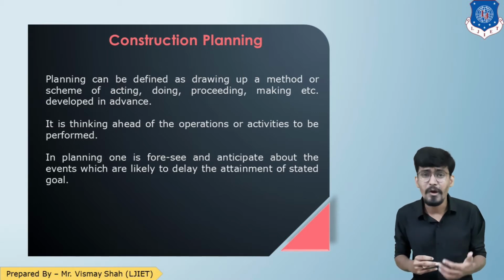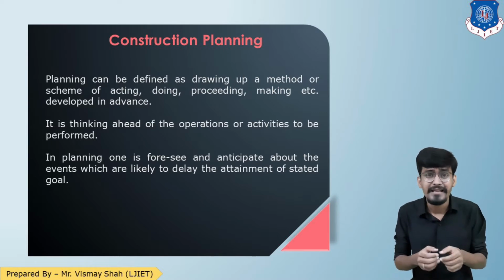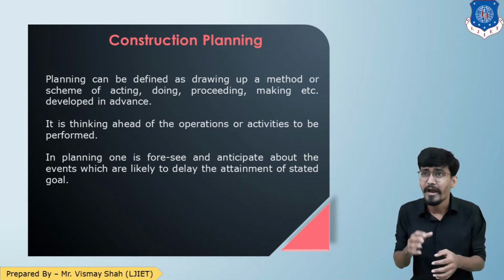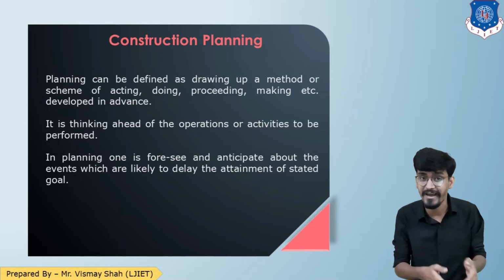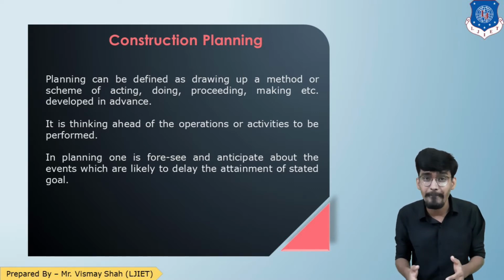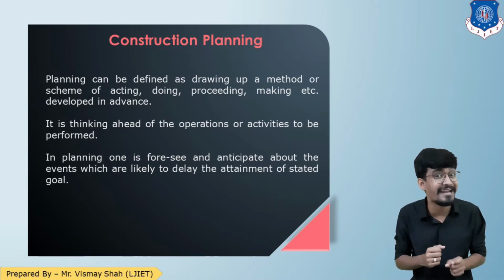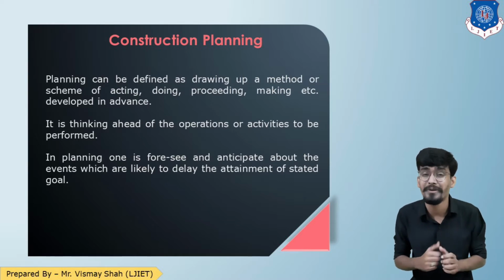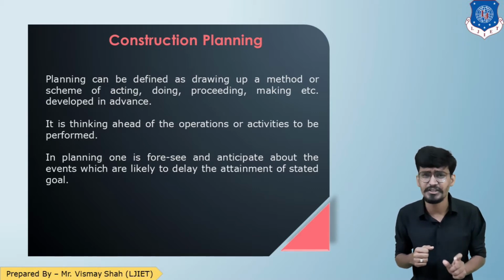Also, if you are planning a construction activity, such as constructing a building just on the Kalupur road or the Relief Road, you have to plan where your material will get stored, or how the construction of the fifth slab will happen, where the RMC truck will come from, or where it will stand, the pumping. So you have to plan and foresee, and we have to see the delays, which activity can get delayed for which reasons, and you have to try to mitigate that. So that is about your construction planning. I hope we are very much clear about what construction planning is.